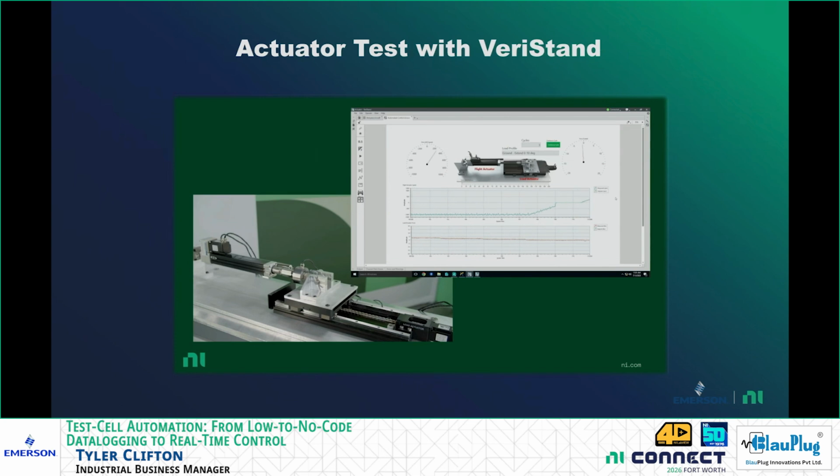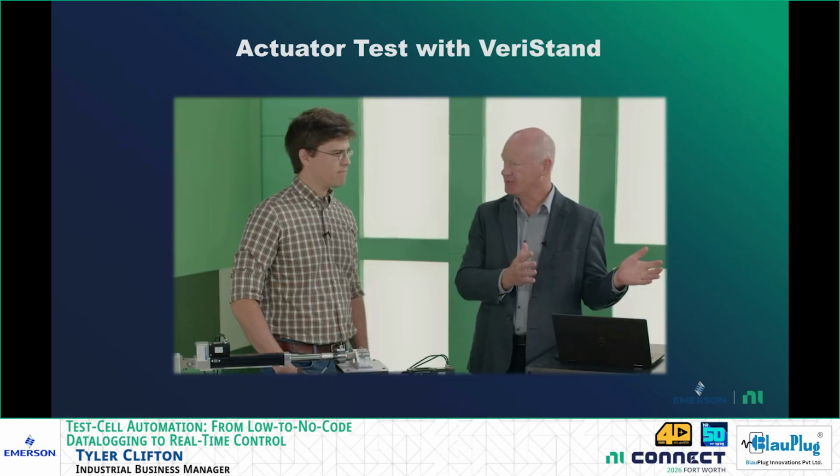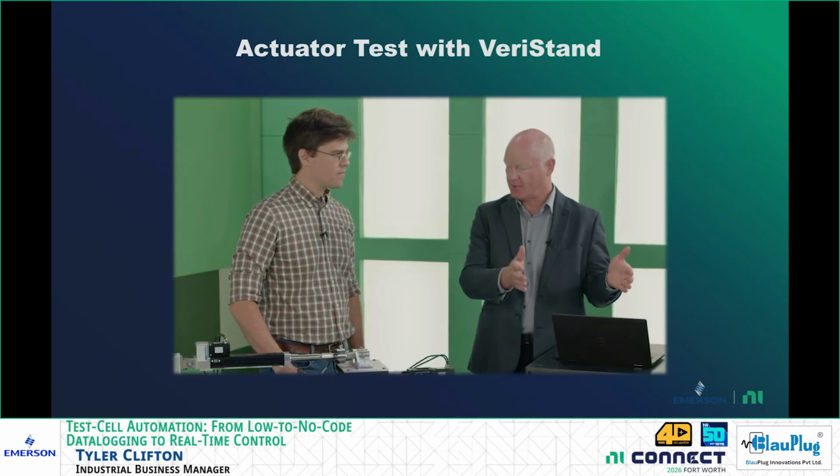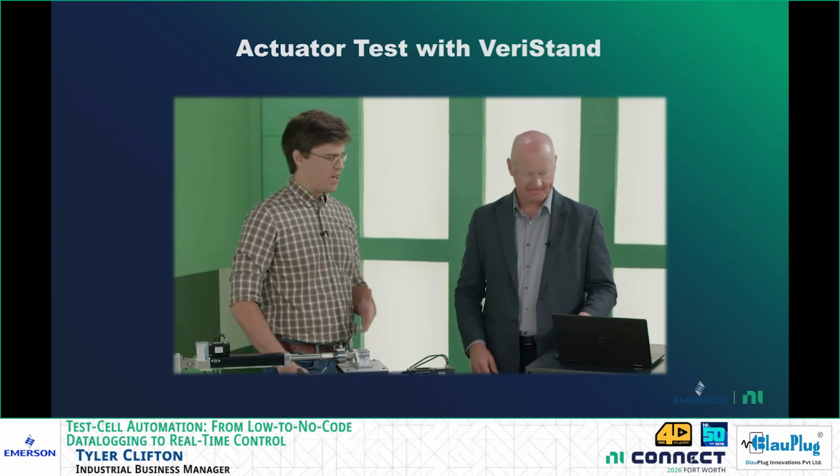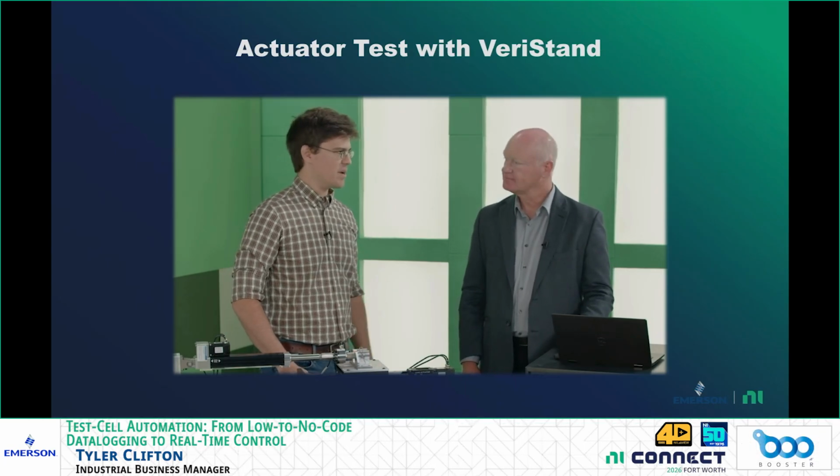So that's the power of VeriStand: it allows you to bring all those different models and controllers into one environment, coordinate among those different pieces, and run them together. TestStand then does the sequencing, saying we're going to run this part of the test now, and this part next, and generates the reports that come from that. Yeah, our pass-fail report, pushing out through a database, exactly.